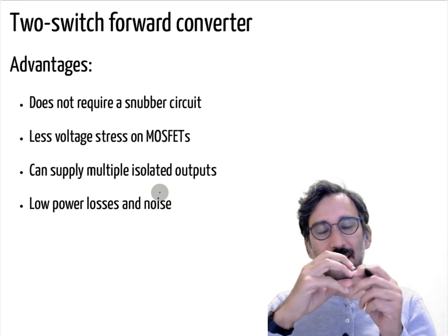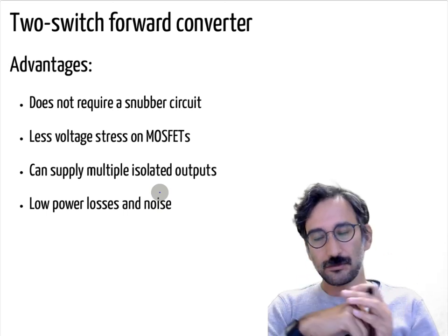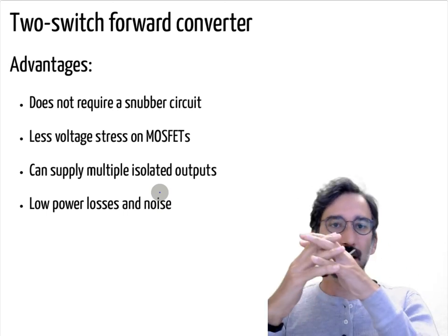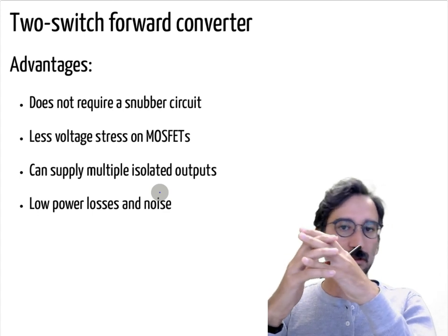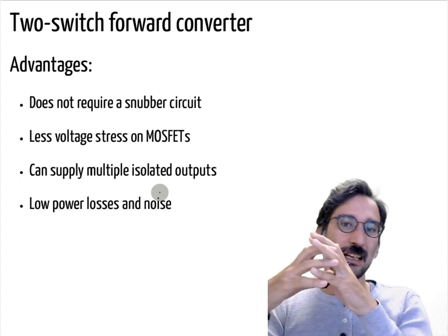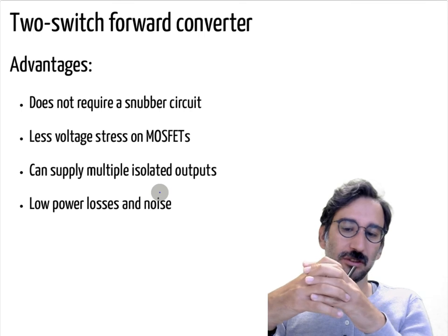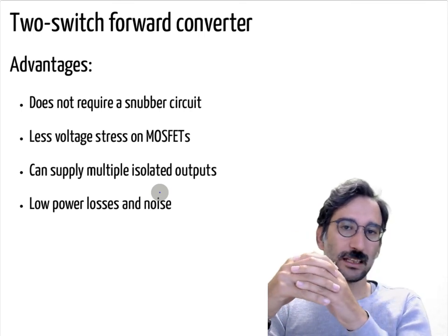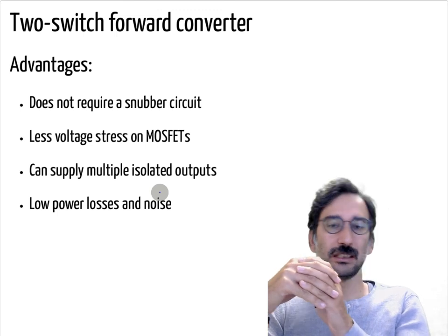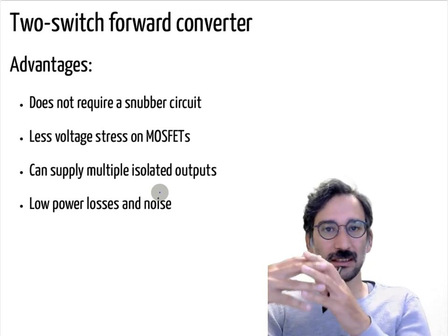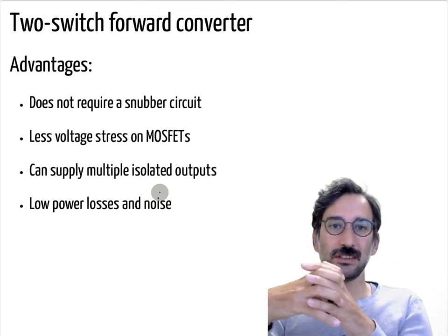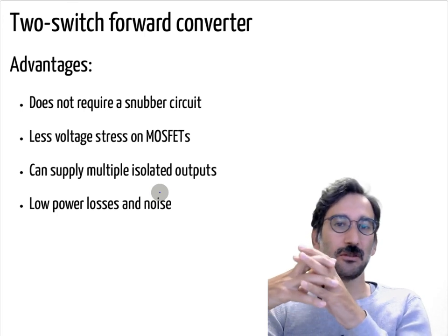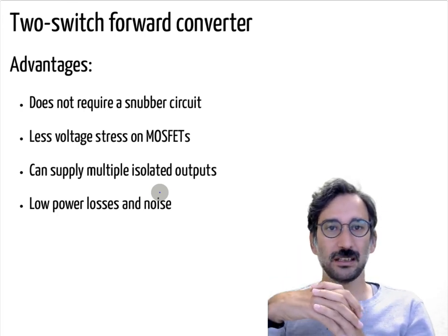Another thing is, once you have the third winding, you can create electromagnetic forces on transformer windings, and if they are not fixed properly, if you have loose connections, and depending on the operating frequency, if it is in the audible range, if you are switching at 15 kHz, your transformers can make a lot of noise.